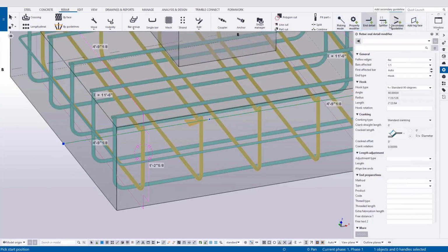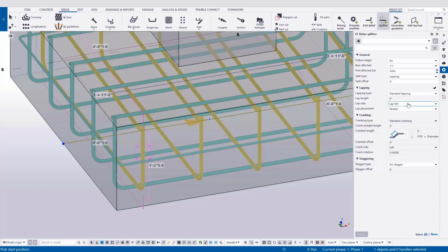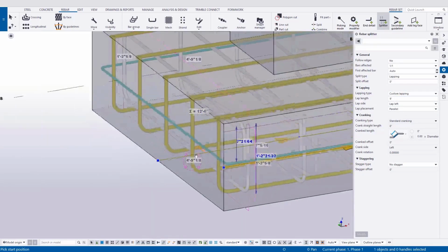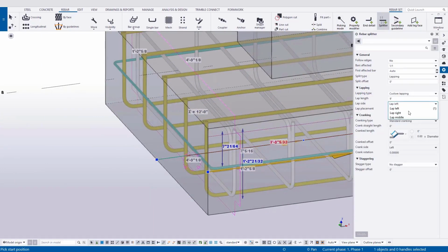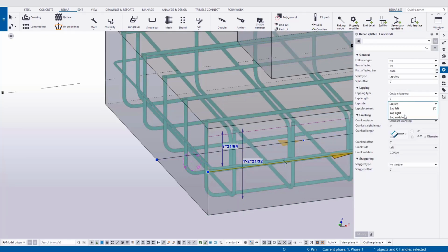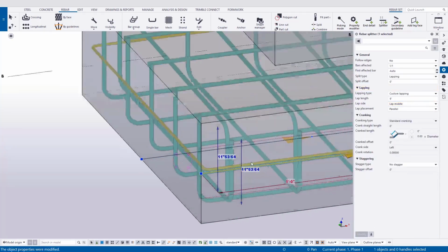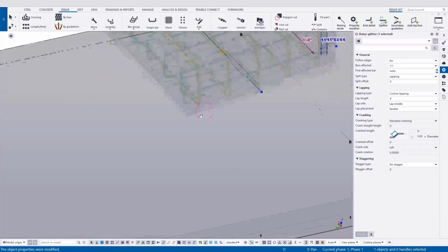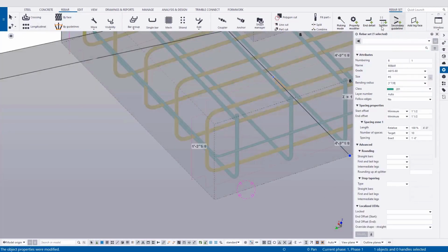Specific tools exist to apply crossing and longitudinal bars or circular reinforcement, or even applying reinforcement by concrete face or even bend shape specifically. Users can work methodically throughout the entire model and detail the reinforcement as they go, providing a high level of accuracy, flexibility, and detail. This approach also lends itself to reviewing the reinforcement as it's being modeled, so it's easy to spot errors or design oversight in interaction in 3D space.